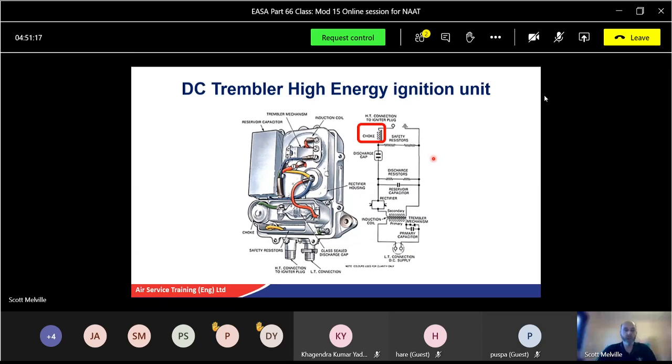If you ever watch the Iron Man films, there's his little power coming out his hand, you see it building up and then going big spark. Well, he's got a big choke unit in his arm. Without that, you will get a spark, but a sort of intermittent, quite weak spark. So this choke unit holds on and prolongs the spark until it discharges itself into the spark plug.